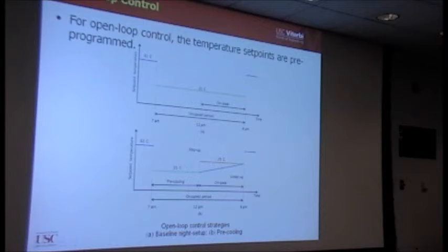Or if you want to respond to the time of use or the price difference between before noon and afternoon, then there are strategies people suggested. Maybe you make a set point change in the afternoon, then you will save energy during the afternoon, and therefore you don't pay a higher price for the afternoon part, okay? Because that's where you have to pay the demand cost.